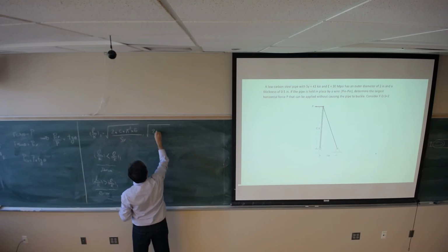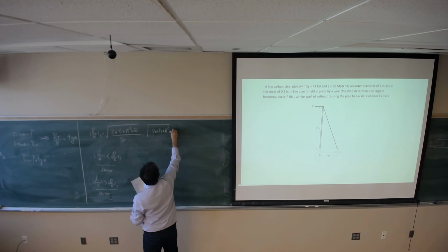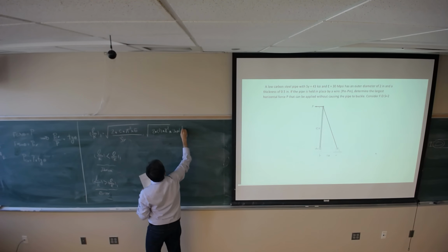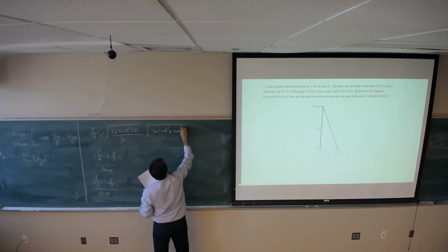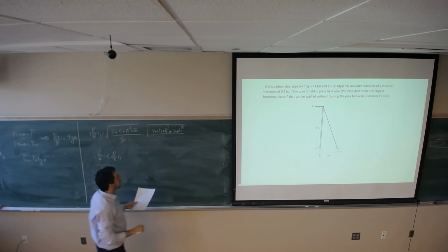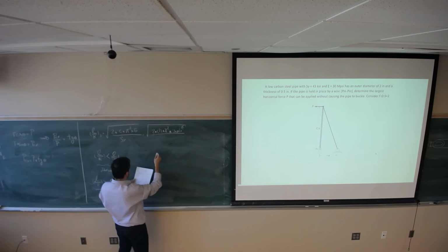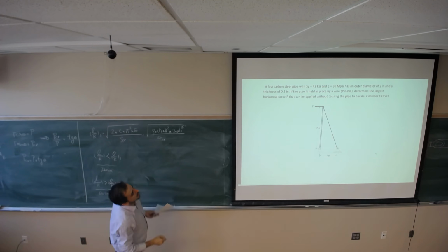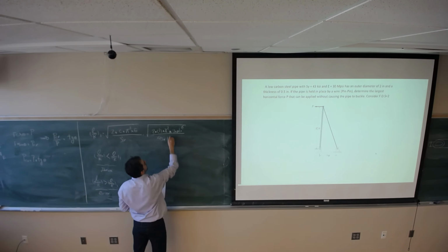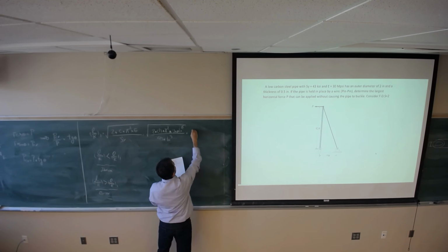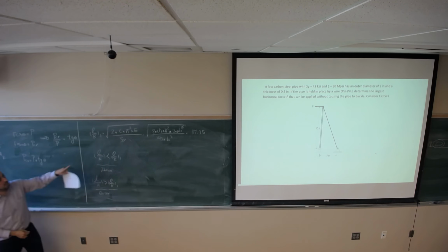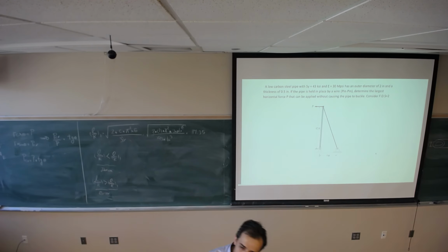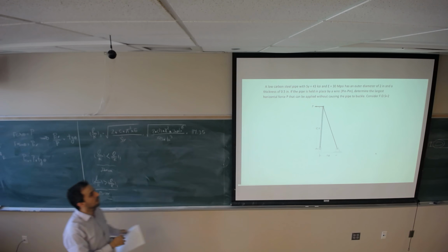So 2 times 1 times pi squared times E, which is 30 mega, that's 30 times 10 to the power 6 psi, divided by 43 kpsi, where kpsi means 10 to the power 3. L over K1 is going to be 117.35. Why is C 1? It's a pin-pin condition. If it was fixed-free, it would be 0.25.